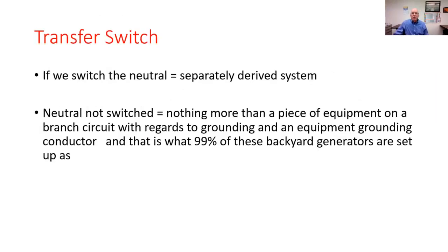Bonding coming up. But you're going to see that with these generators, if we switch the neutral, that means it's a separately derived system. Well, we're not switching the neutral in these backyard Kohler and Generac generators.